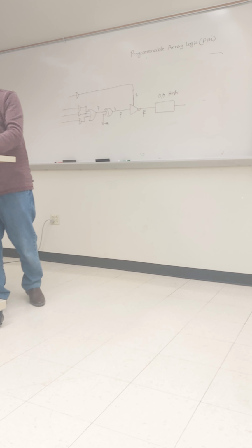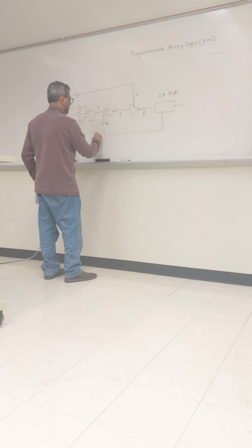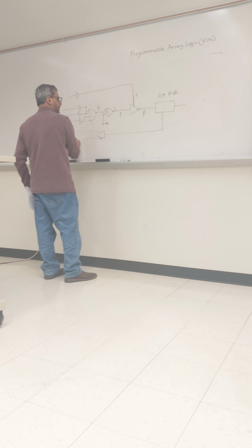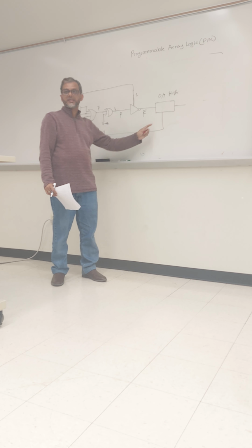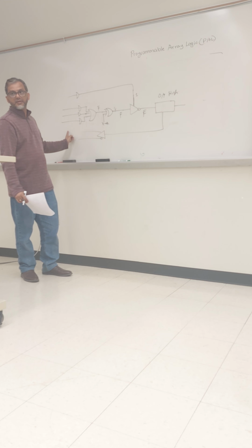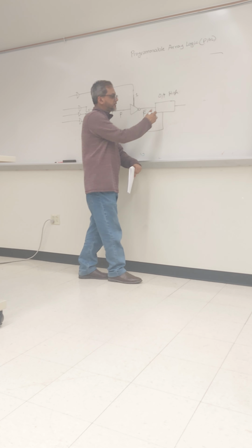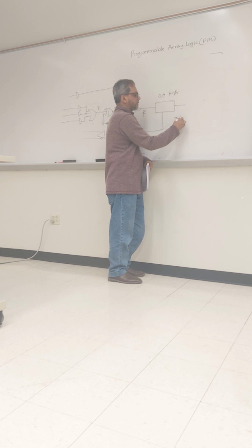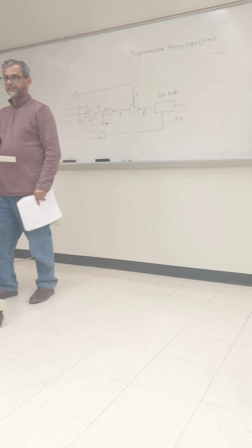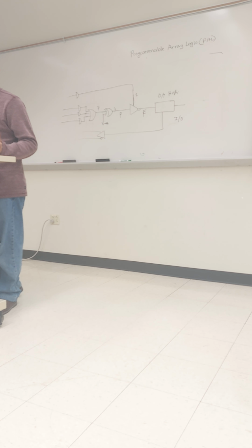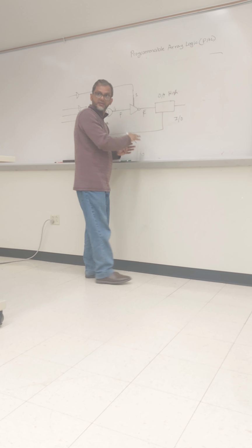And then, if you have this detached circuit, what actually happens is it has something like this in the PAL circuit. Then you can actually give a return path, a feedback path, you can give some input to the AND array. So if this happens in this PAL circuit, this node is known as an input-output pin. You can give input, also you can take output, I/O. So it can increase the functionalities. So this whole portion is actually the macro cell. Okay.